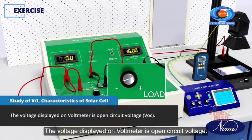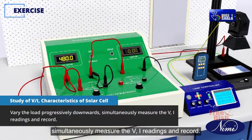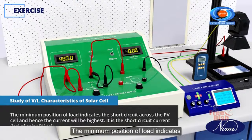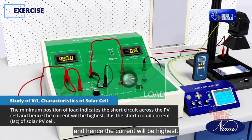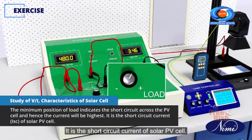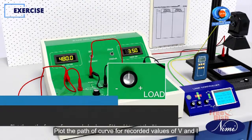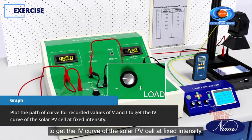The voltage displayed on the voltmeter is the open circuit voltage. Vary the load progressively downwards. Simultaneously measure the VI readings and record. The minimum position of the load indicates the short circuit across the PV cell and hence the current will be highest. It is the short circuit current of the solar PV cell. Plot the curve for the recorded values of V and I to get the IV curve of the solar PV cell at fixed intensity.